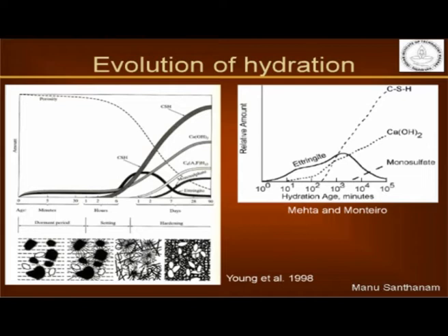As hydration progresses, more and more of the space gets filled up, and you ultimately get a space that has very little void content. You have occupied almost the entire water filled space with hydration product, because of which your strength continues to go up, and that strength going up corresponds to the CSH, which continues to go up.